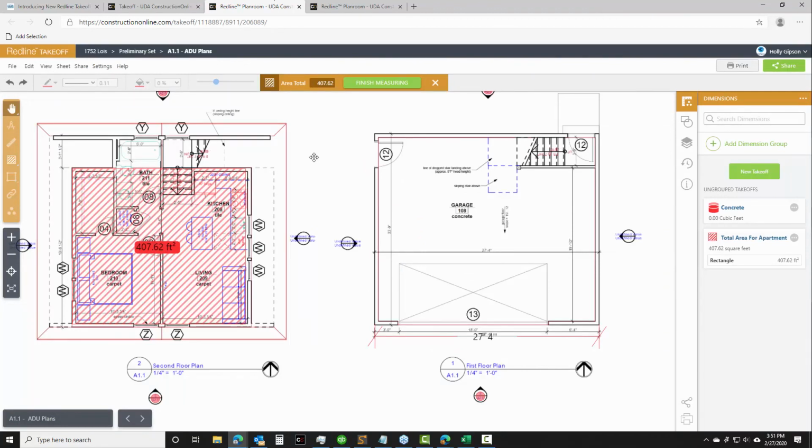Okay, I did see one question. I did want to point this out. Someone said that they arrived late, but they were looking for a way to shift the measurements to metric. We have a lot of clients all over the world, and this is incredibly important. This is how you prevent disasters from occurring, both minor and major. Make sure that your measurements are set to your corner of the world's measuring standard. You can change that through the settings menu here at the top, and you can change the measurements to metric. You'll also have that option when you're setting the calibration tool. When you're first setting the calibrator, there's an option to switch from imperial to metric, or vice versa, depending on where you're working or who you're working with.